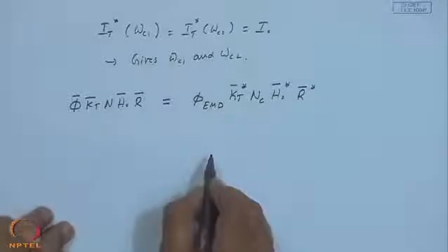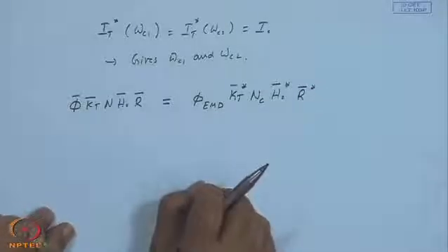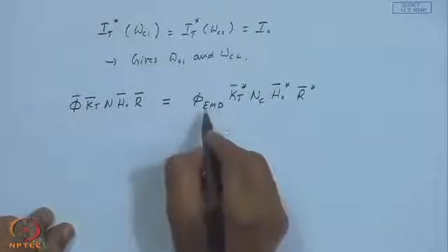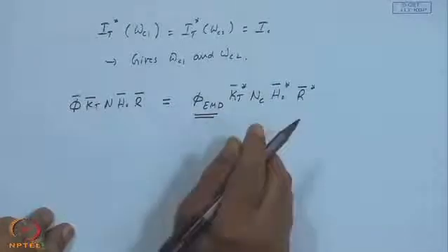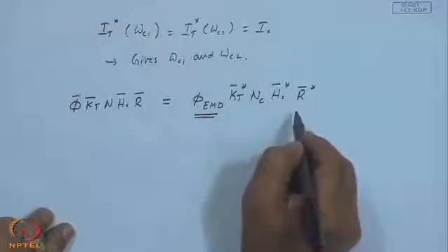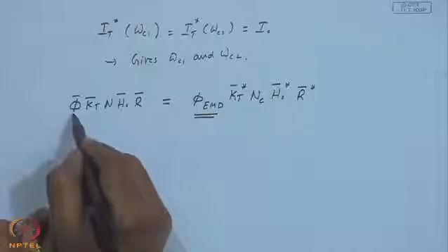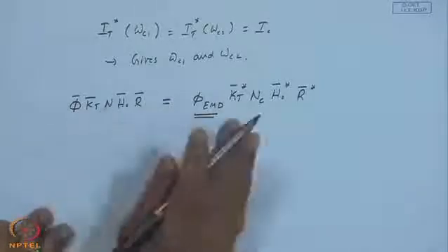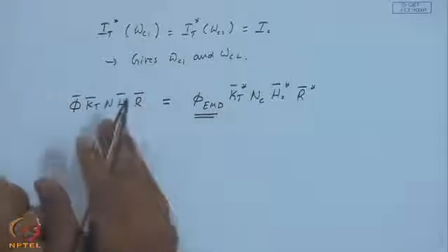What we realized is the solar radiation available above the critical level, be it based upon the equivalent mean day of the average days with KT greater than KT minimum, or all the days with the monthly average daily utilizability phibar with corresponding n, should be equal, because the other days are always less than the critical level and they do not contribute to any solar radiation falling on the collector surface above the critical level.